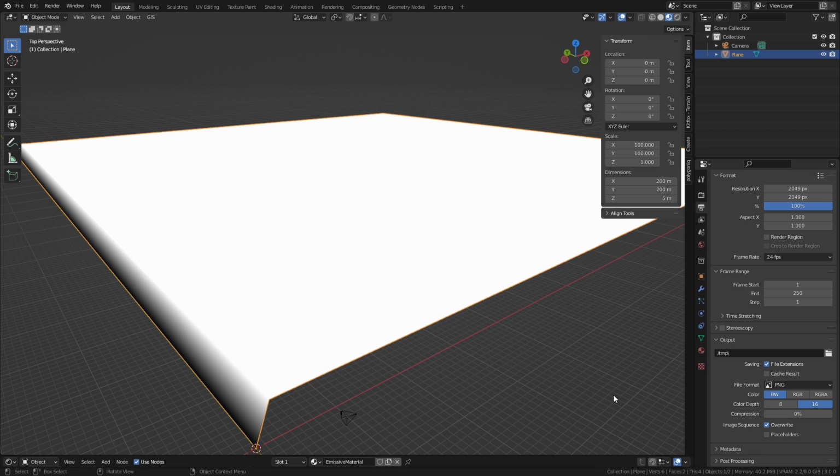That's what you use in MX Bikes. It requires the .raw file extension converted from Photoshop or GIMP. If you're using the Resolute MXB Track Builder helper, we're going to leave it as a PNG because the helper will convert it to raw for you. So you can skip that whole step of going to Photoshop or GIMP to do that conversion to raw. Just leave it as PNG. So again, we have that all set up here, and let's go on to our next step.